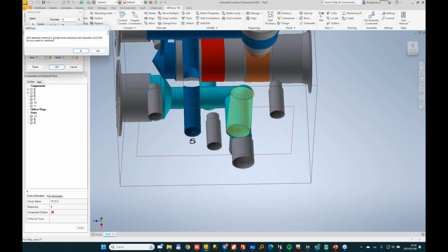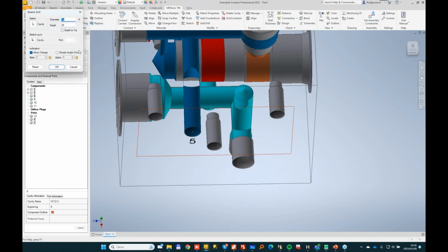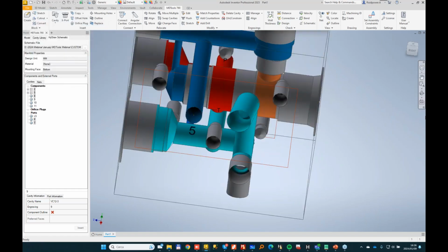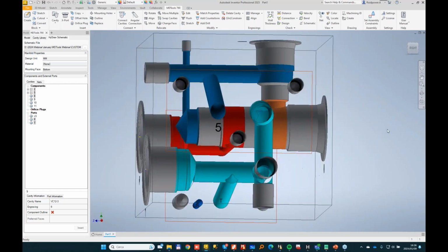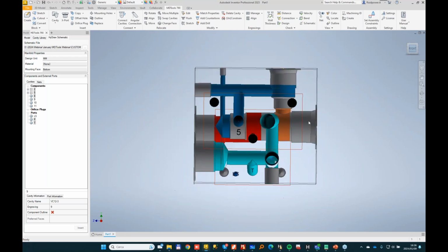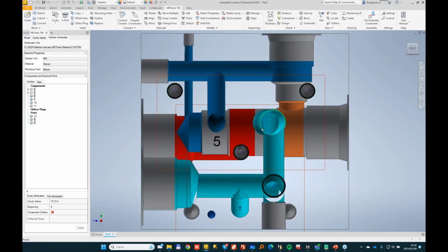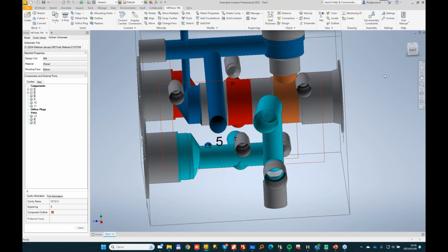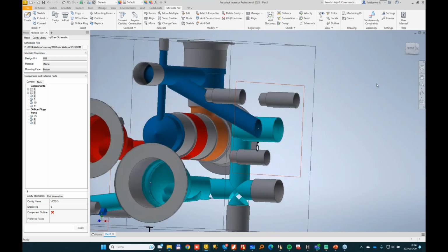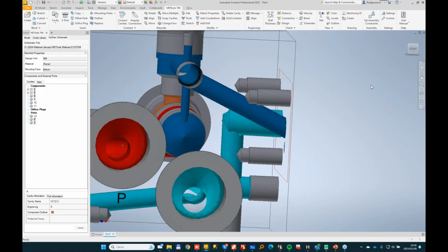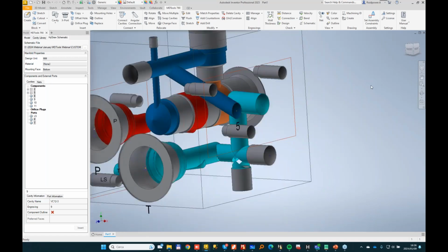This is doable. Again, we have the verification of maximum drill diameter. In terms of manufacturing, this can be a problem, because as you can see in this face, we have inclination going up and going to the right. So if you have a 5-axis machine, you will be able to do it without any issue. If you have a 4-axis machine, this will require an additional setup, which may cost a lot of money. So pay attention when you do inclined drills, because you should take into consideration also which machine will be used to make that particular block.